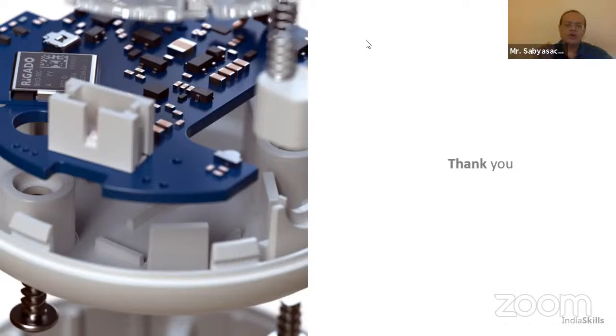Oh yes, of course. The basics, if you're looking at casting, such as draft angles, are more or less the same. If you're looking at pressure die casting, it's pretty much similar. But if you're looking at sand casting, the concepts are the same, but the details vary. The amount of work that you have to give changes completely. Sheet metal is again a completely different line of thought.